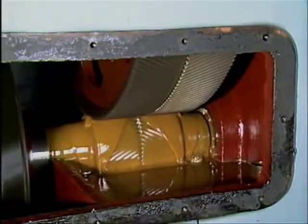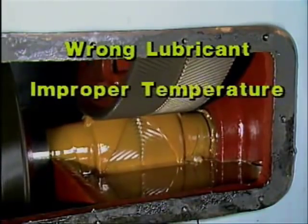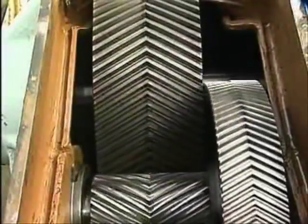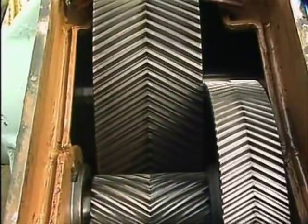The basic causes of lubrication problems for gears include using the wrong lubricant, improper temperature, contamination, and insufficient lubricant. One of the prime indications that a lubrication problem has occurred in a gear train is something called scoring. Scoring is a scratching or tearing of a gear's tooth.